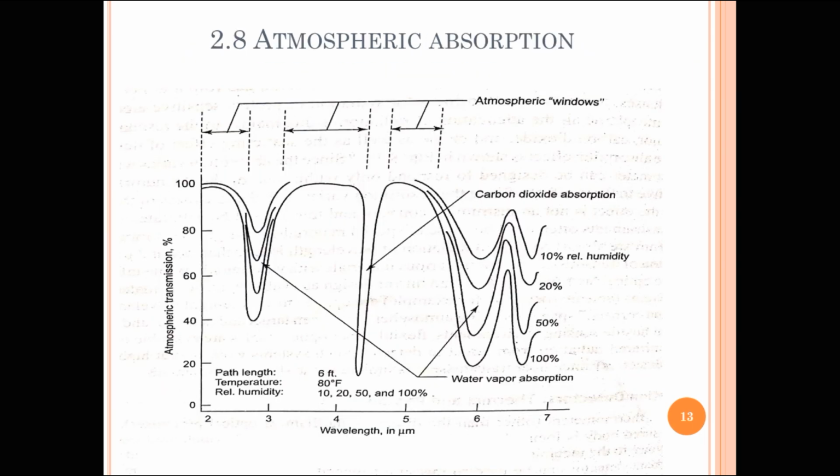Atmospheric absorption. Another source of error is the losses of energy in transmitting the radiation from the measured object to the radiation detector. Generally, the optical path consists of some gas, often atmospheric air, and various windows, lenses, or mirrors used to focus the radiation or protect sensitive elements from the environment.